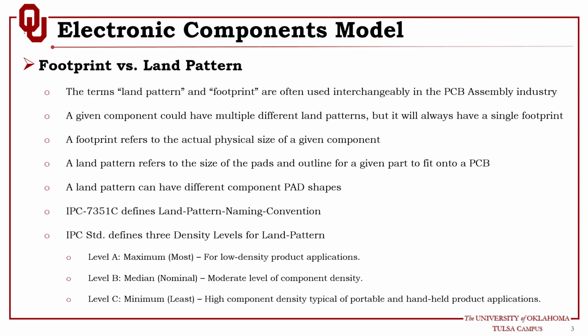And when we do automatic footprint creation today using the IPC standard or IPC compliant wizard, you will see that the IPC compliant wizard will suggest a name according to the naming scheme or naming convention defined in this standard. So you can go with it, or you can change it and edit it manually. So it's up to you, but it's always good to be in compliance with the standard.